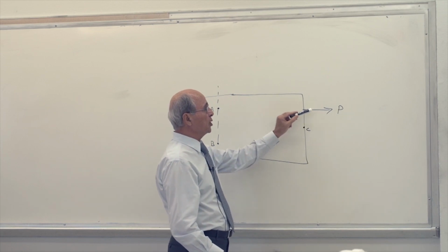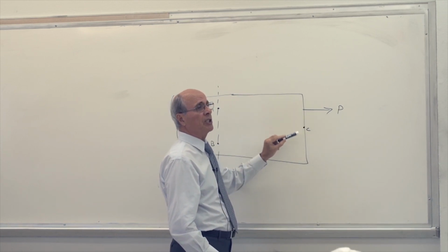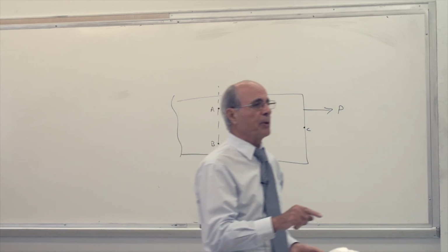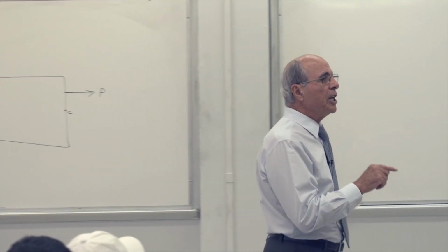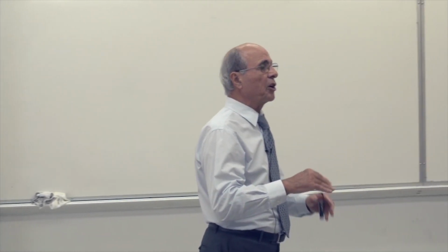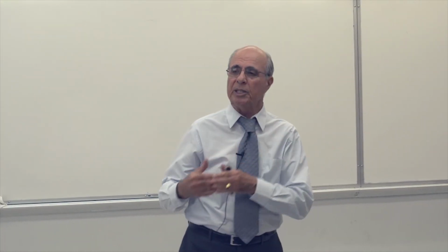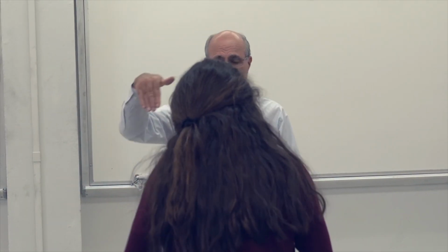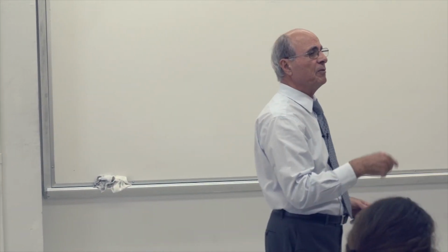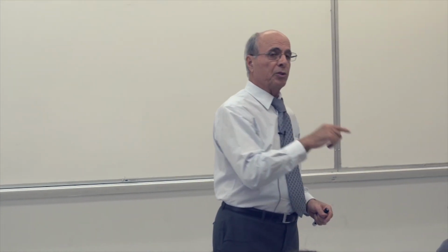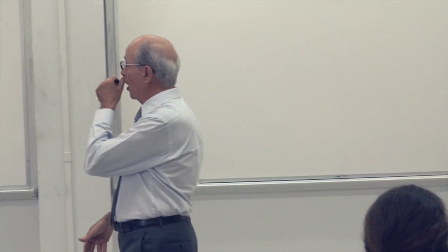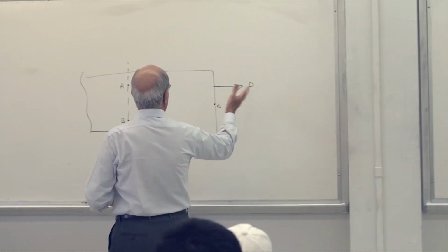You can change this force P from this location to that location. When you do that, you are not using equilibrium. You are using an equivalent system, because these are external loads. This has nothing to do with the internal load. And you learned in statics, if there is a load here and you want to take it out from here and put it here, you have to replace it with a force and a couple. So that indicates the direction of your moment. However, in most cases, you don't need to do that.